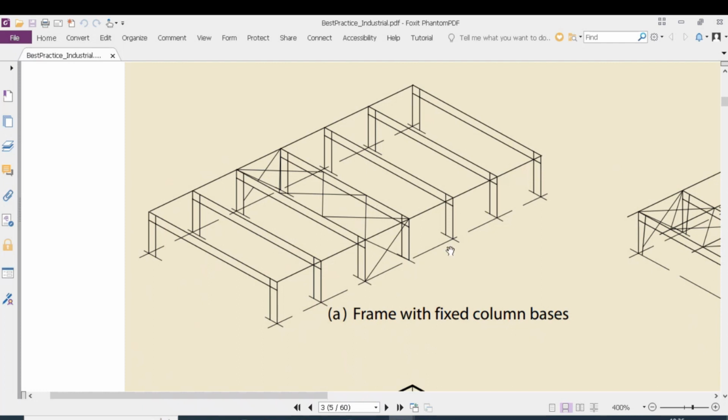Now in this figure, we have a braced truss provided at the roof and vertical trusses provided at the walls. In case of lateral load applied out of plane to the portal frame, it will be attracted by this stiffer bay. The lateral load will be transferred to this stiffer bay roof, and from this horizontal bay it will transfer it down to the ground via the vertical truss system or vertical braces.